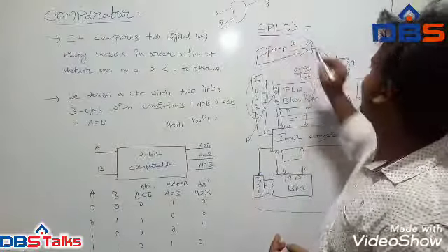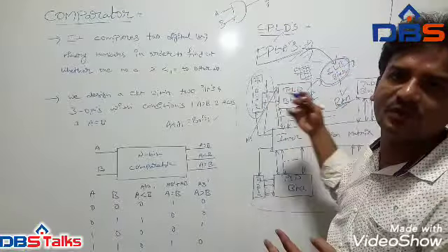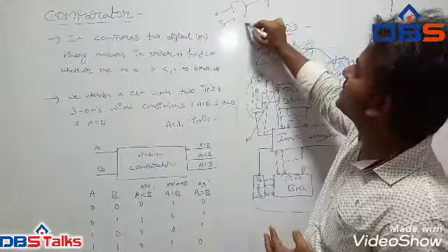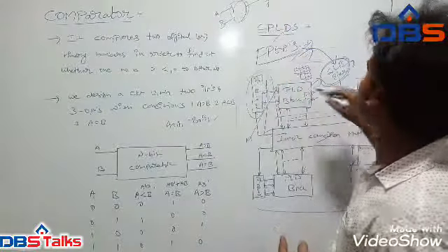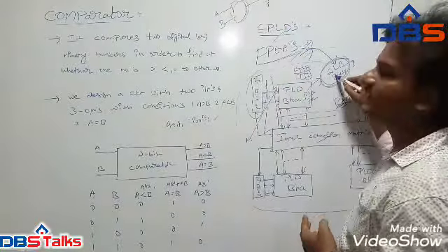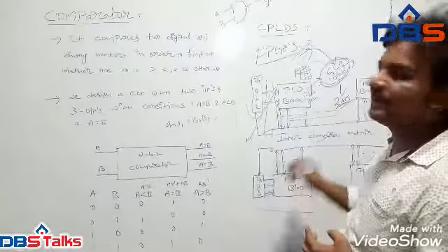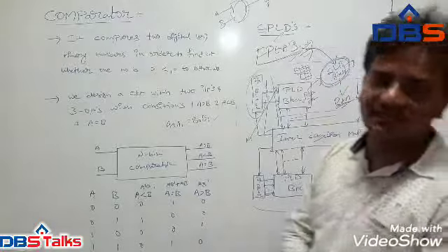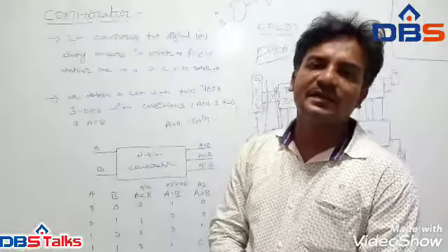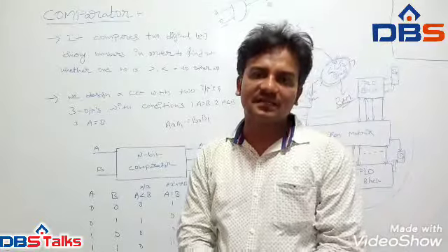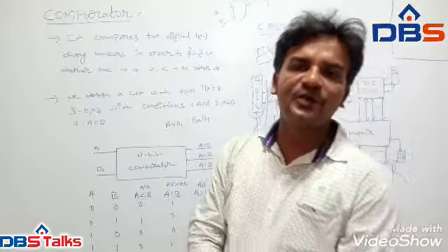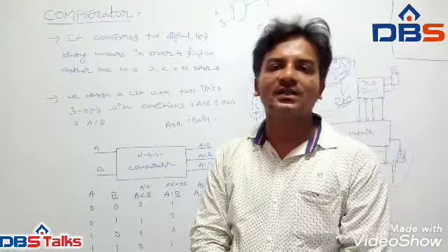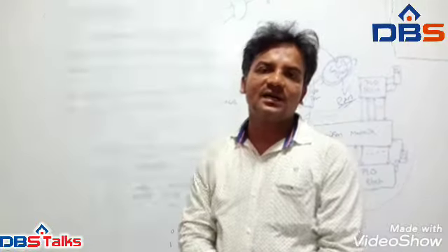When we perform this functionality within a CLB block, we check it. That means whenever we do the simulation within the CLB, we check whether the functionality is performing successfully or not. That is possible in the case of FPGAs, but not possible in CPLDs. And synthesis produces a gate-level netlist for the overall design.